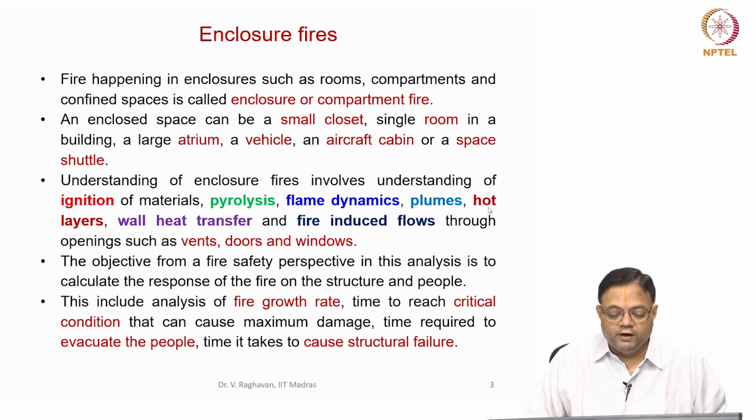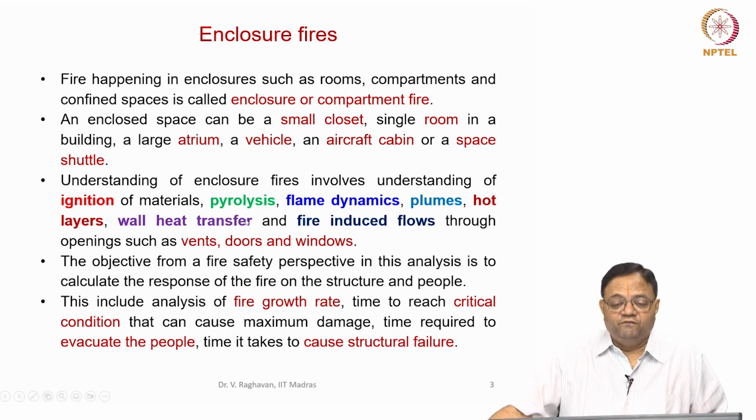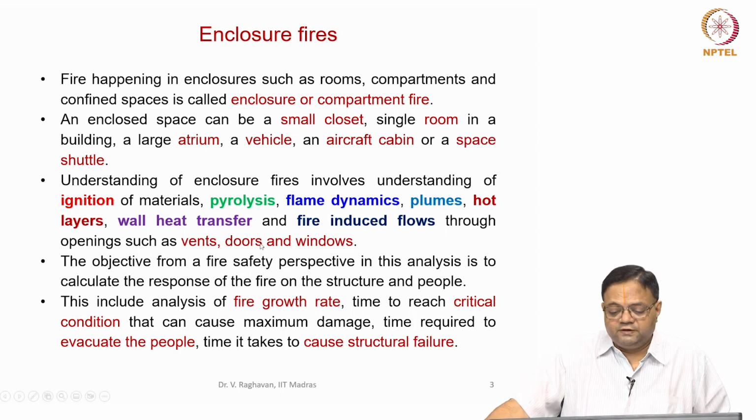That involves wall heat transfer, and due to the temperature differences, which cause density differences, fire induced flow will occur. These are all dictated by the vents, doors or windows in the enclosure, and how much they are open. That means several factors which we have discussed so far are required to analyze an enclosure fire.